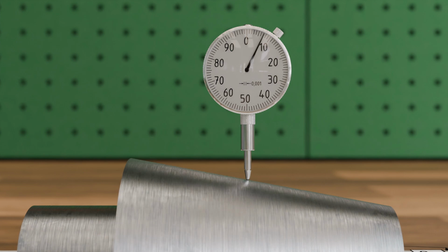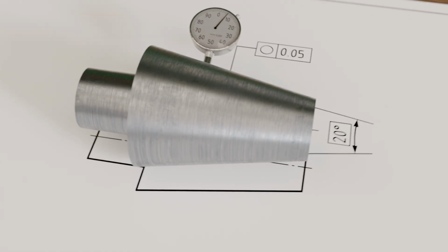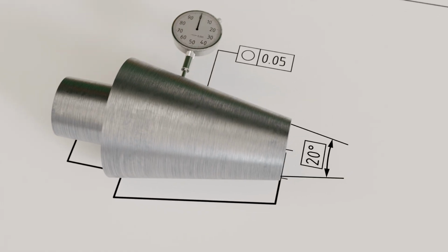Therefore, when tolerancing roundness of non-cylindrical surfaces, it is necessary to specify whether the roundness refers to the direction perpendicular to the axis or perpendicular to the surface. This is where the direction element indicator is applied. In our case, we want to tolerate the roundness perpendicular to the part axis. Therefore, we first need to specify the centerline of our cone as the datum. To do this, we place datum A directly in line with the dimension line for the cone's included angle, which in our case is 20 degrees, so that the datum does not refer to the cone surface, but to the geometry element derived from it, that is the centerline.